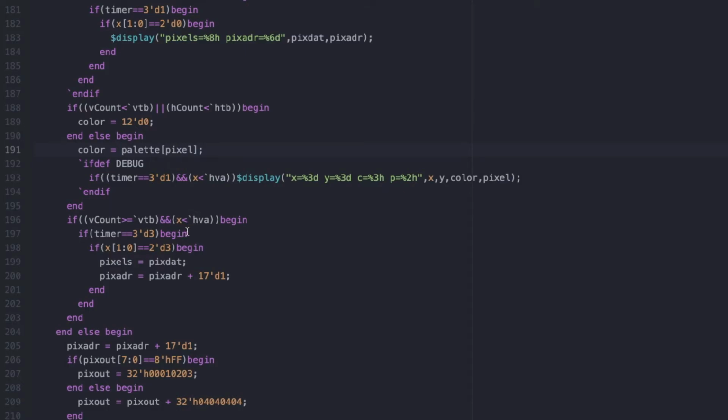And that way, when it's negative, it's not less than this. It's greater than, because there's no sign bit. There's no sign bit at the left side of the data, and so it's a positive number, and it's bigger than 0. And so it's much bigger. It's bigger than 640. So that's what this is doing, it's checking the horizontal 640 to X, not H count. And that way I can tell if it's on the visible side of the display.